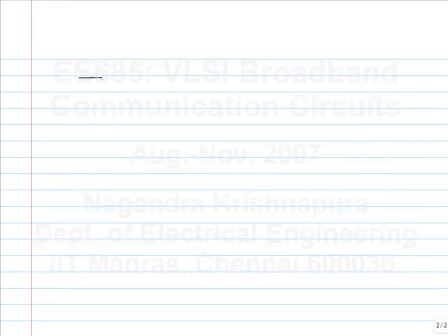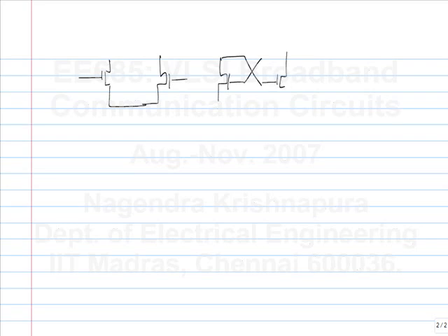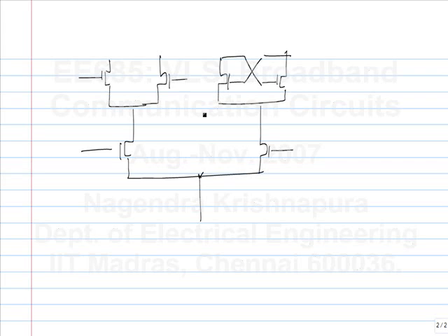This is a slight practical problem. If you remember the circuit, generally you want the clock to be strong enough to flip the circuit from one side to the other. So if the data is of low amplitude or corrupted too much by ISI, then you may have a bit of a problem. Okay.